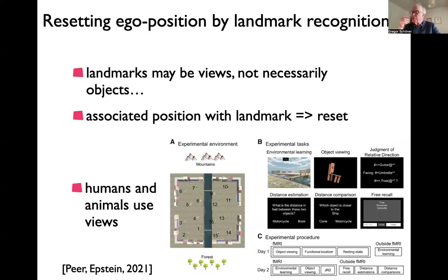And then the resetting is typically done by having some map. So, for instance, having landmark information so that you know, oh, now I'm in front of that church, now I know where I am and even how I'm oriented. Even though you're maybe not exactly in the spot you predicted, you're close enough to the church to reset, and now you can start afresh in your dead reckoning from that corrected location.